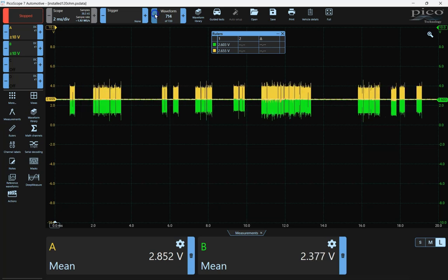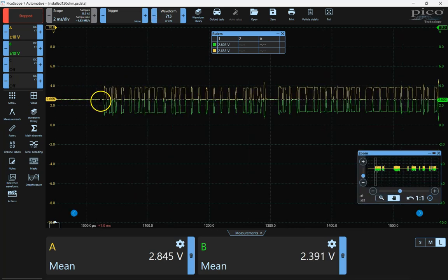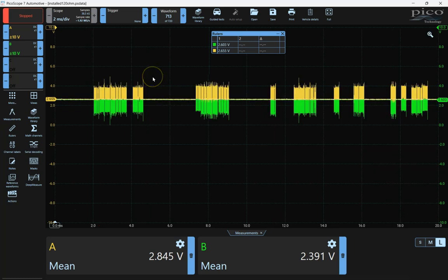I don't have any error frames. All communication is restored. So the machine, even though it was designed with active termination, in this case, I put a 120 ohm terminating resistor across CAN high and CAN low, towards the middle of the bus someplace, definitely not where it's supposed to be. But just for testing purposes, I was able to determine I don't have a problem with this machine as long as my termination is functional.